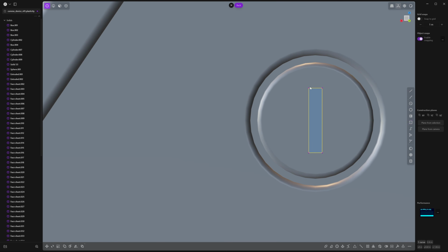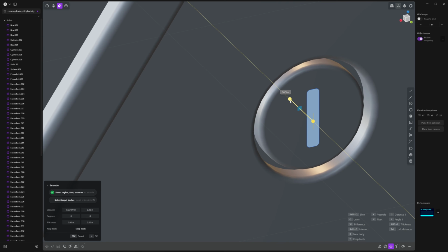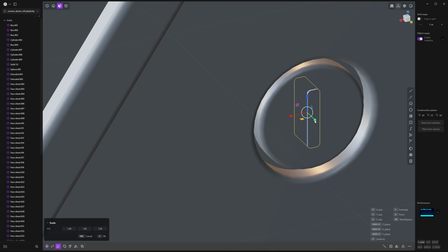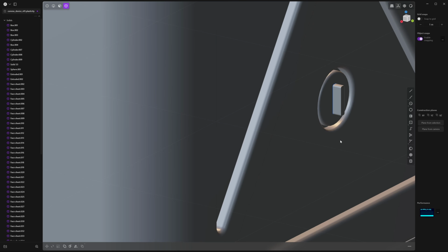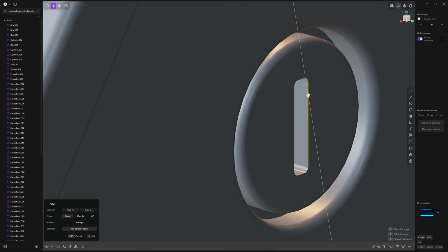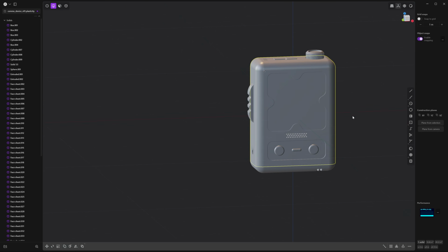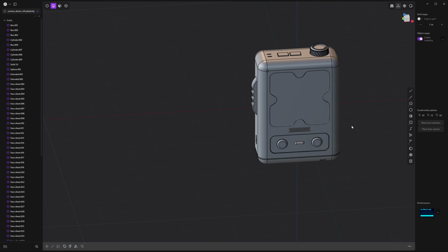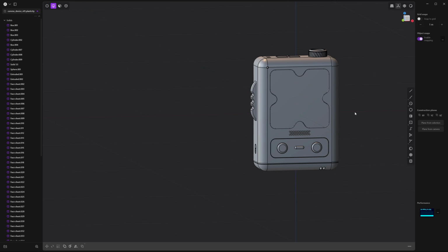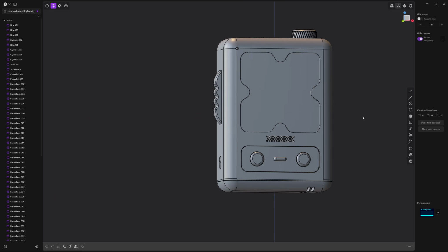So I'm just creating a rectangle, pressing 1, selecting these points and filleting them out. Press 3 so we kind of push this inwards. In body mode, select the main body, shift select this, and right click to accept. I'm just going to fillet this. Great. So this is just one method to kind of block things out. You can definitely experiment by modeling as you go, but sometimes it's easier to just kind of see everything as graphic shapes and then move those and then use Booleans.